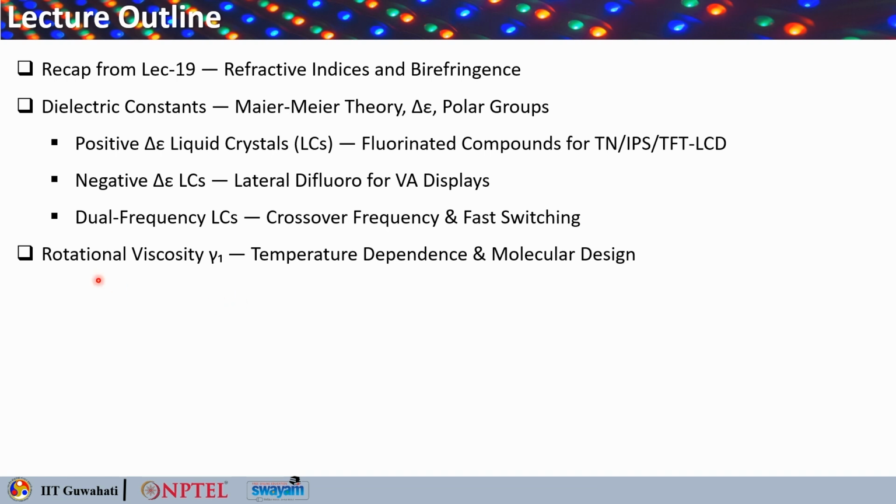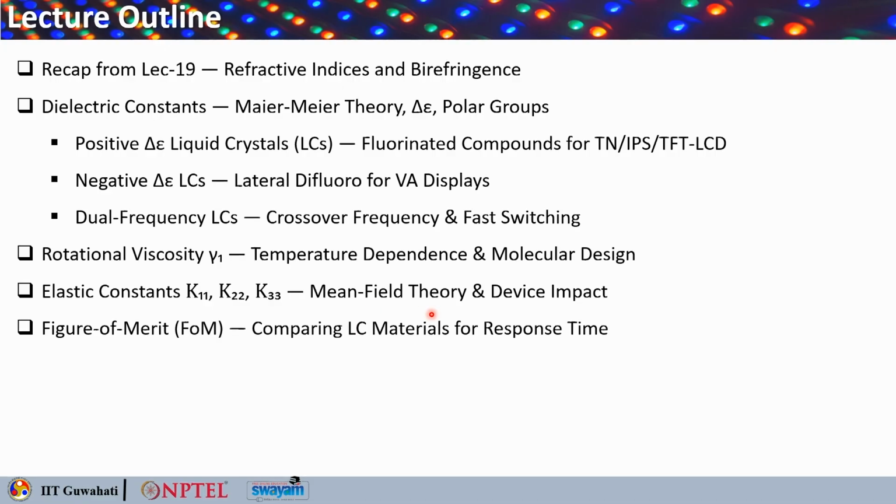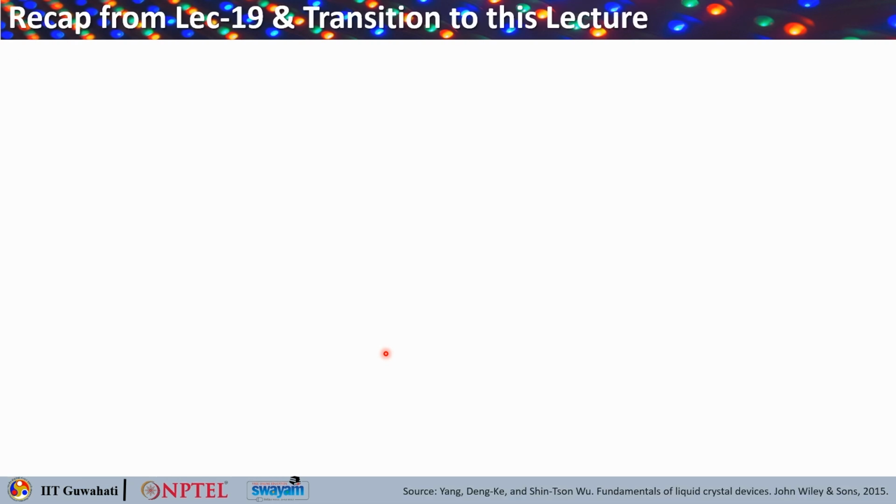Then we will focus on the rotational viscosity gamma 1, study its temperature dependence and the molecular design, and invoke the elastic constants K11, K22 and K33, and see them from the mean field theory and the device impact point of view. And the final figure of merit will compare the liquid crystal materials for the response time. So, here is a brief recap from the previous lecture and the transition to this lecture.